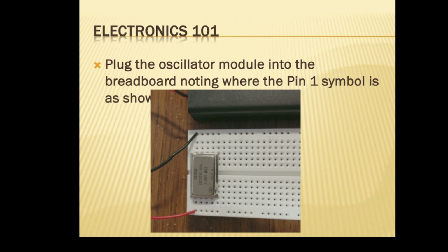We'd have to play with these two capacitor values there to get a better value. I'm sorry, I plugged in the wrong place anyway. That makes sense if I hook it up in the right place. Okay, there we're still modifying quite a bit. We got it into a triangle. Put the small right value cap back in there, and that would actually smooth it up. It'd be pretty close to sine waves. Not bad. First official circuit, I guess.